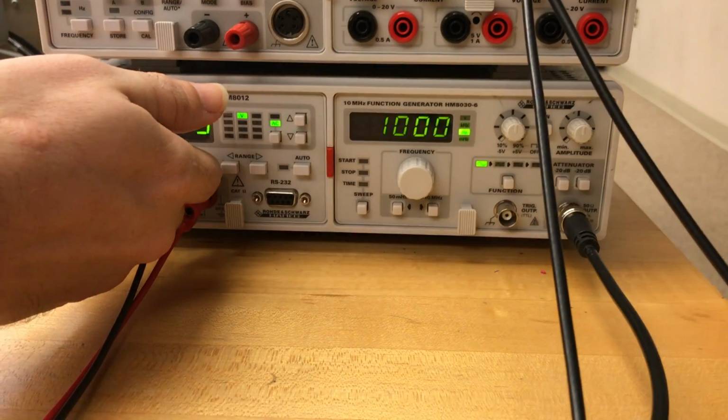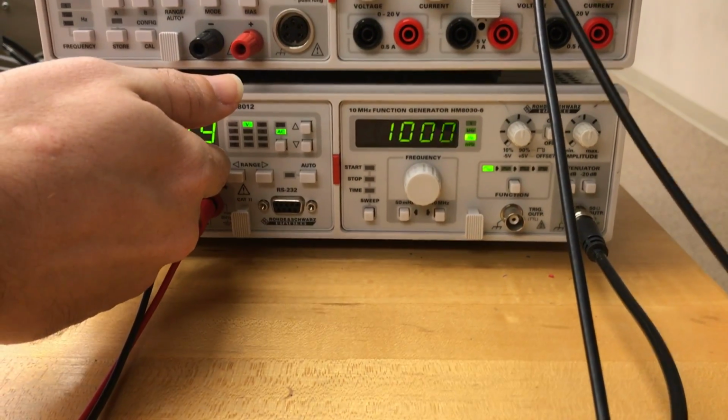Right, so now that you have your circuit built, the very first reading you can take is actually your VRMS over the resistor 2. You can see I have my multimeter connected to resistor 2, and our reading is 2.649 volts RMS across that resistor.